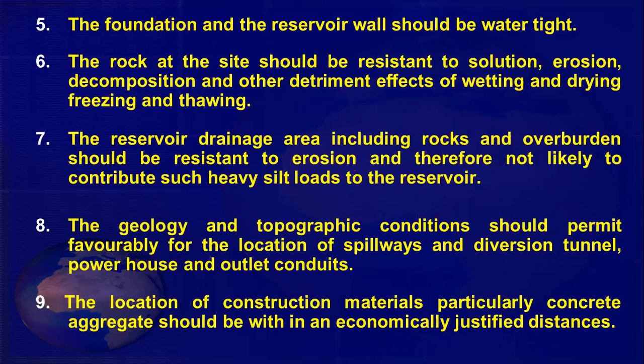The reservoir drainage area, including rocks and overburden, should be resistant to erosion and therefore not likely to contribute heavy silt loads to the reservoir. This overall area should be resistant to erosion, because there is always a possibility that erosion will take place because of the huge weight exerted, as well as the water flow.